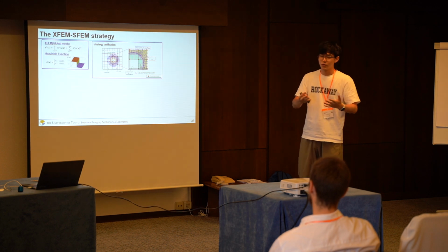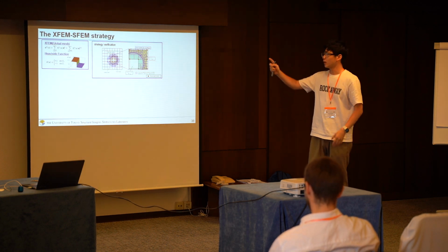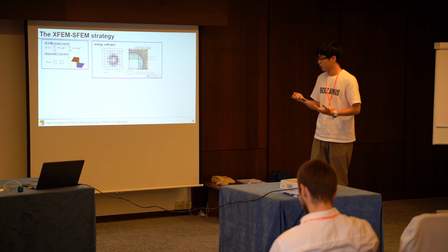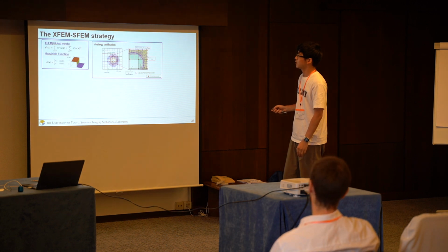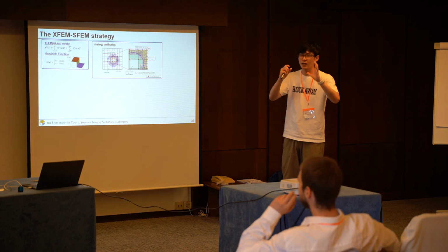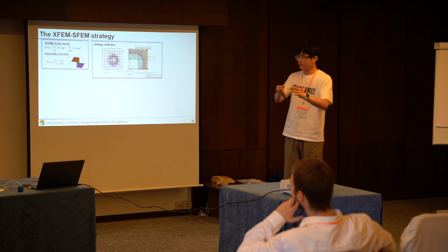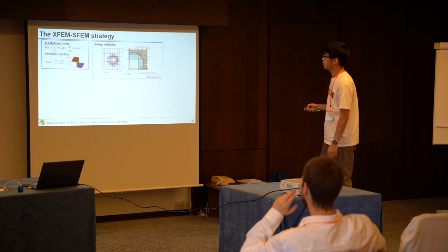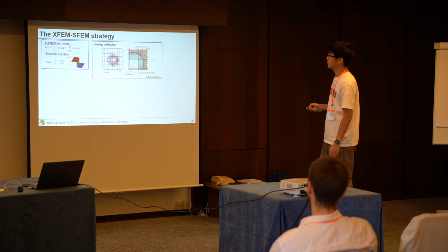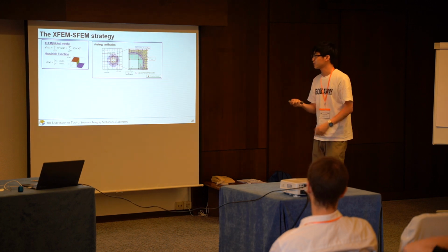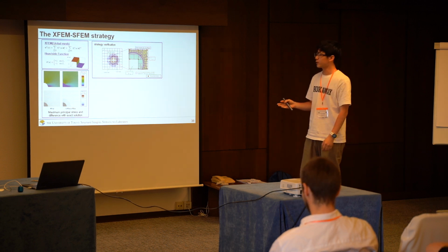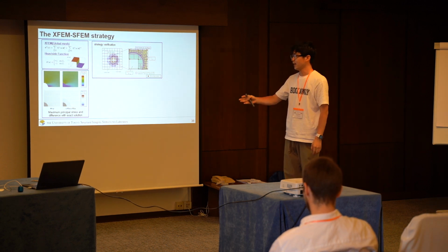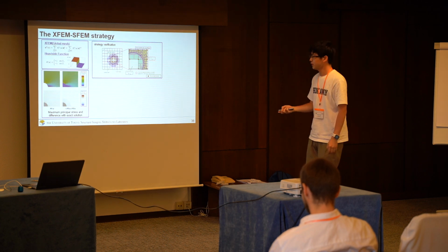we applied it to a very simple plate model with a hole whose exact solution has already been known. Right? And when making the mesh, you can see the global mesh. When we make the global mesh, we didn't consider the hole inside. The global mesh is just applied to the entire domain, including the hole. And after we make the mesh, the discontinuity surface can be simulated with the Heaviside function. And we compared the result with the standard FEM and also with the analytic solution.